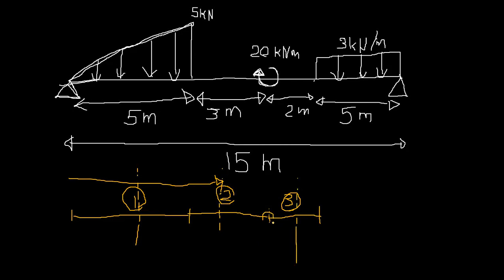After the bending moment, within this region you don't have anything other than the UDL. So I'll consider 1, 2, 3, 4. So I need 4 equations to mathematically idealize the behavior. If you idealize only from this, it is not continued after 5 meters.